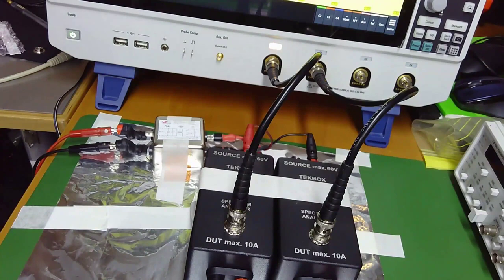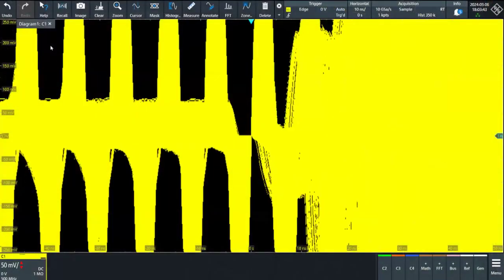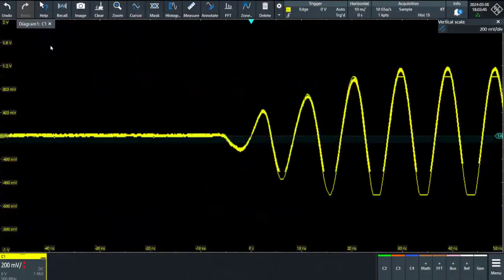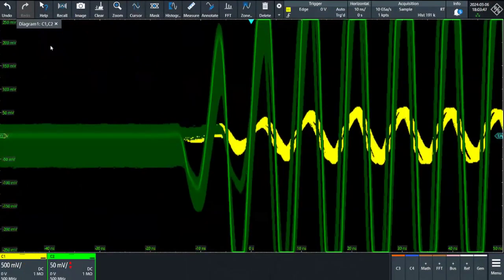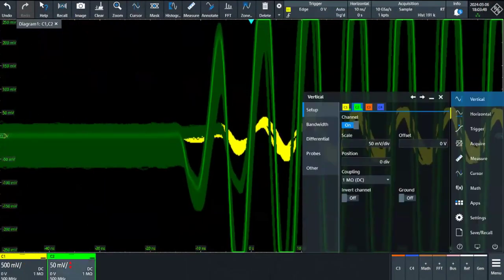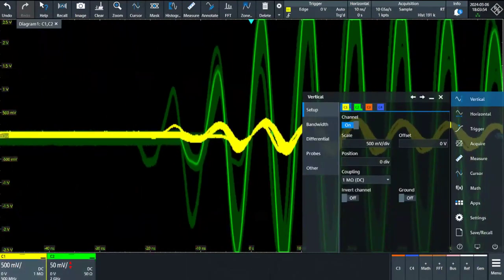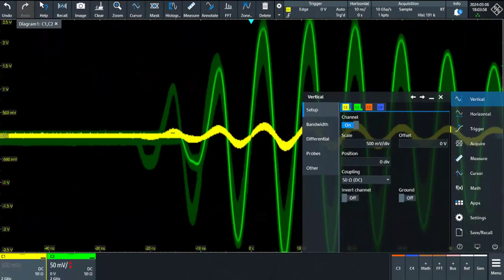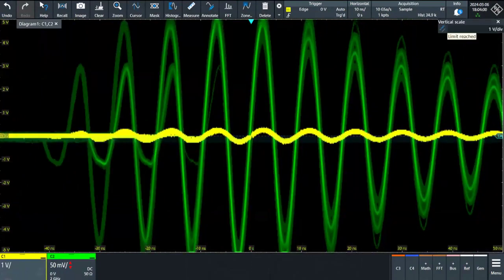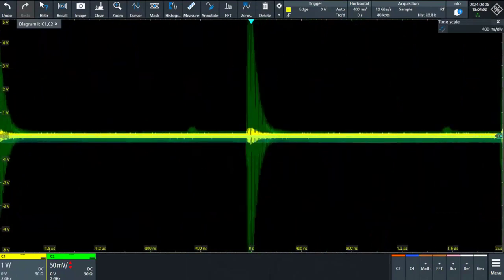And then what we see is this. Let me see. What we see is this. This one, okay? So let's activate channel number 2. Let's review that in channel number 2, we have 50 ohms. And let me check that in channel number 1, we have 50 ohms. It's very important to have 50 ohms in both channels. Okay, something like this.